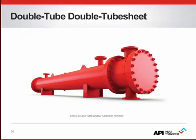The double tube sheet design looks very normal from the exterior. One would assume it's a simple TEMA NEN or BEM type exchanger, but inside is where all the engineering comes to the forefront. A unique arrangement of multiple tubes and tube sheets creates a layer of leak protection that can allow the end user to rest easy on applications where a cross leak of fluids simply cannot be tolerated.